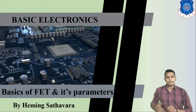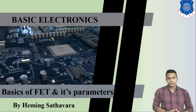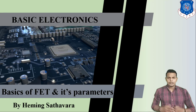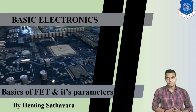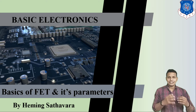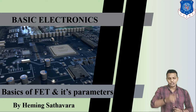As we discussed about BJT, there is thermal runaway in BJT and UJT. So, what is thermal runaway first? Thermal runaway means if temperature increases, due to this there is an increment of collector current. Due to this collector current increment, power dissipation is generated, and due to this power dissipation, heat is produced, and due to this heat, there is an increment of temperature. So this is basically a chain.